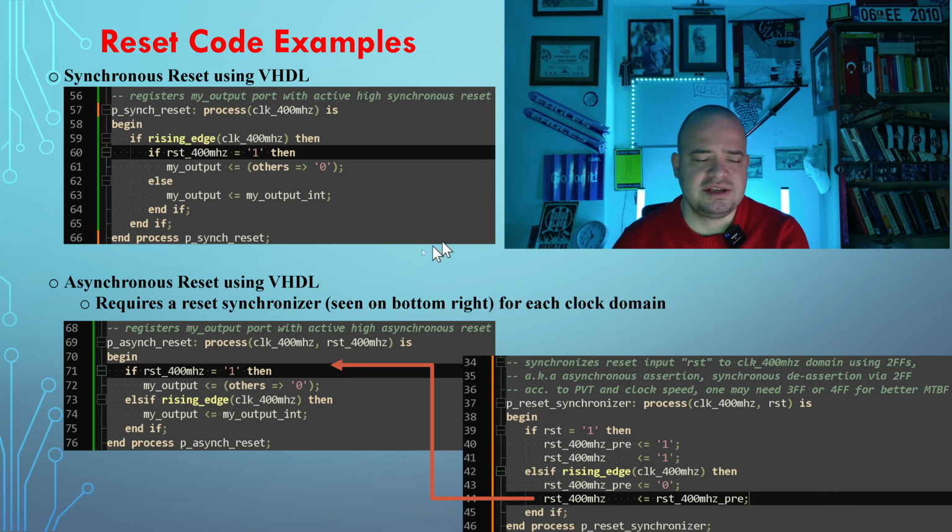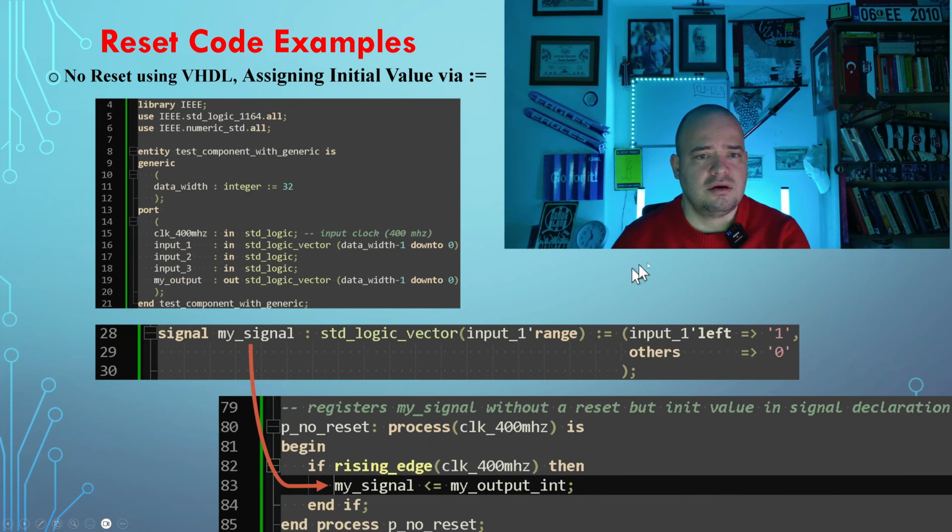Then you will be optimizing placement and routing, your resources, and you will improve your maximum frequency, Fmax value. Okay, this one is actually the most preferred case. Unless you need it, don't reset the signal. Like this one, for instance, this is some internal signal.